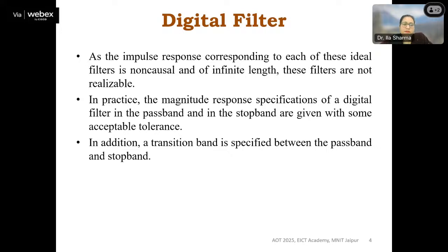So there are some observations. As the impulse response corresponding to each of these ideal filters is non-causal and of infinite length, these filters are not realizable. First observation. Second, the magnitude response specification of a digital filter in the passband and in the stop band is given with acceptable tolerance. There is some specific value given to it, and in addition a transition band is specified between the passband and the stop band.